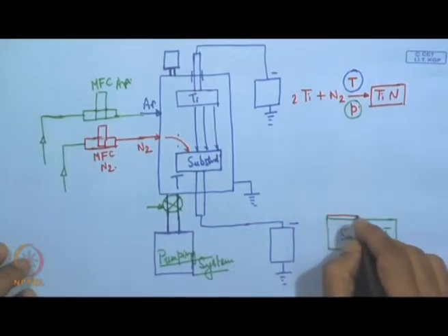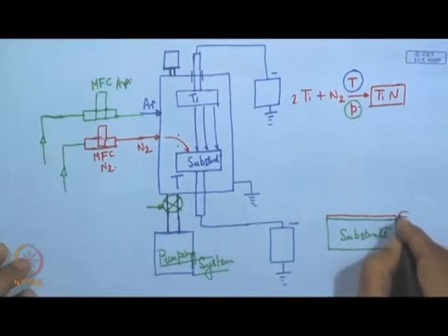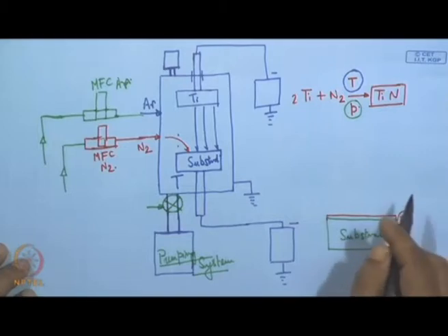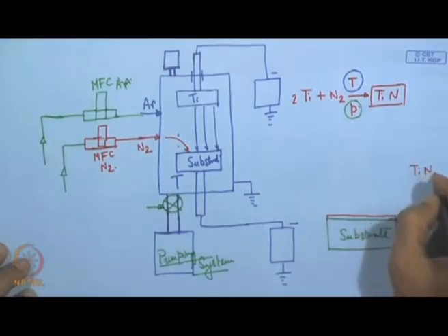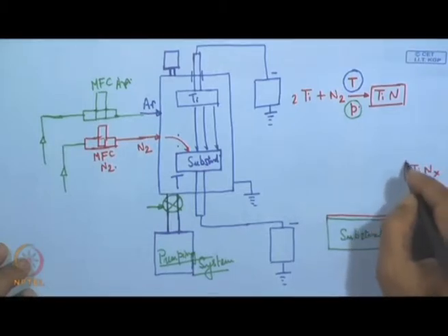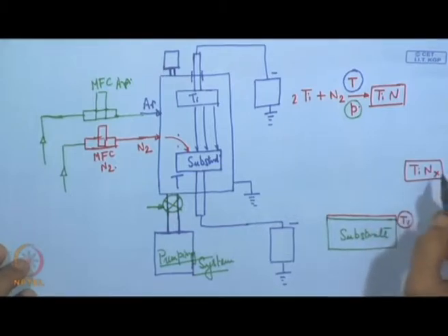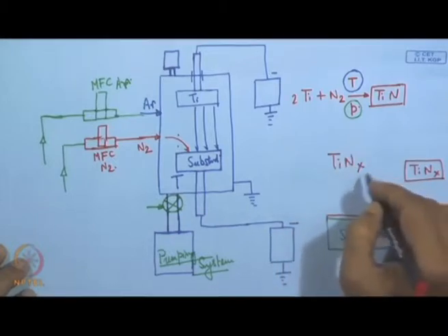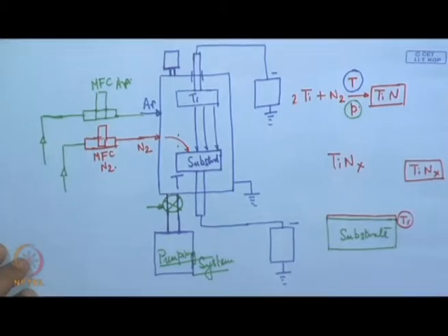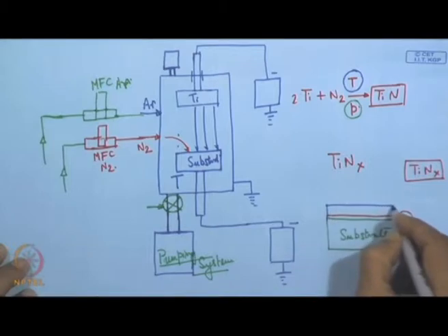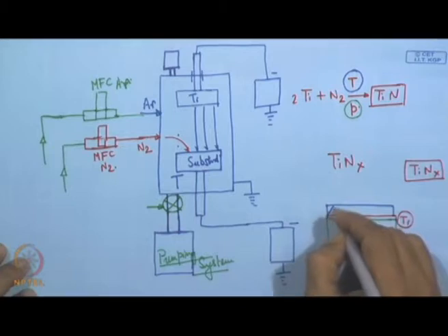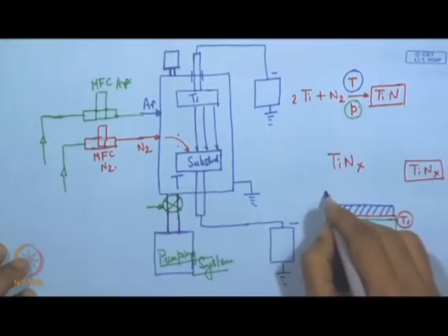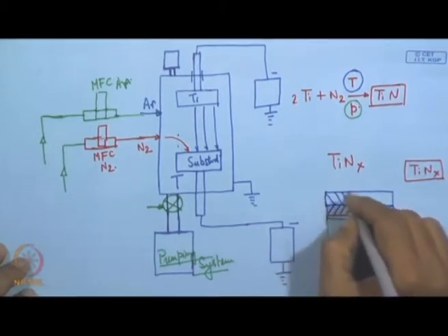It can start with a nanometer-level titanium, just metallic titanium on this, and gradually the percentage of titanium and nitrogen can be properly controlled, so that finally it is going to be a graded structure with the X value gradually increasing, and from titanium to titanium nitride we can have a TiNx, where the value of X will keep on increasing. Within this, when we have a sufficiently grown layer, this is just a graduation of the property, and over that a stoichiometric TiN can very easily be built.